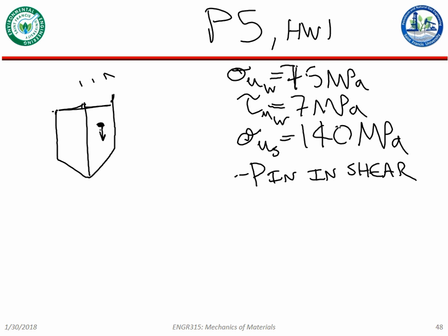I have to worry about a couple different kinds of stress. One is the block, just looking at it, is in tension, correct? I'm pulling down at the center of the block and I'm holding the top of the block up. So we need to worry about normal stress.